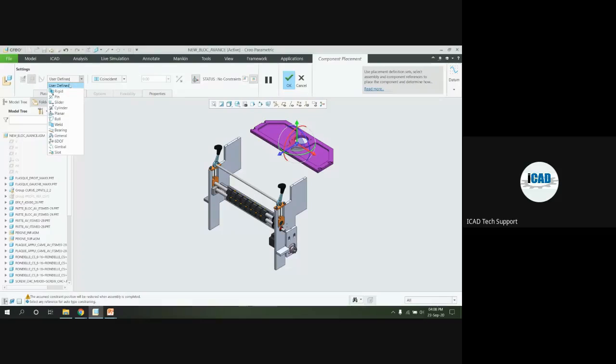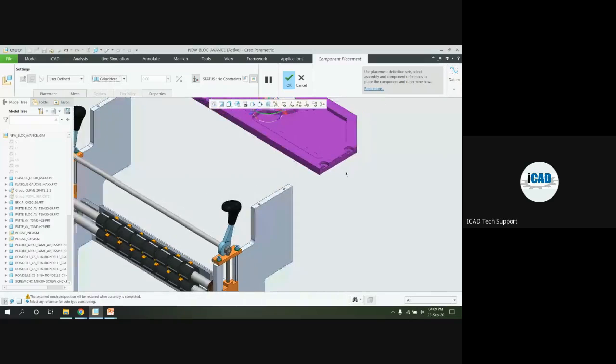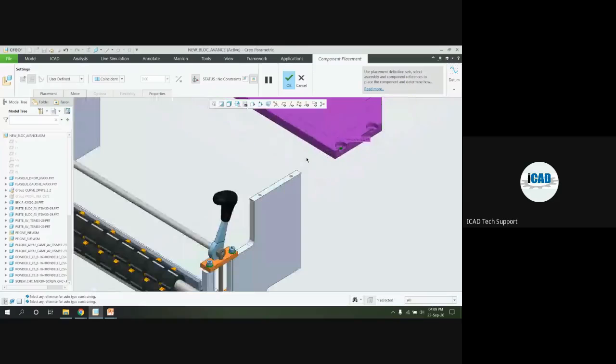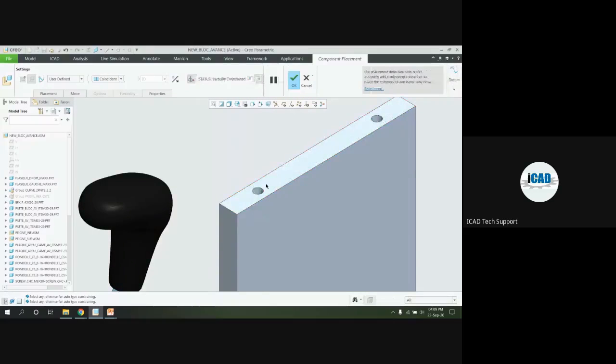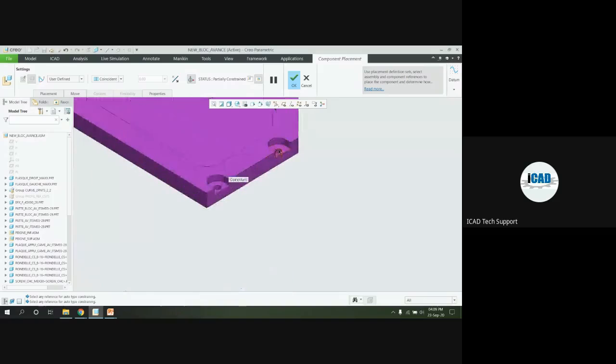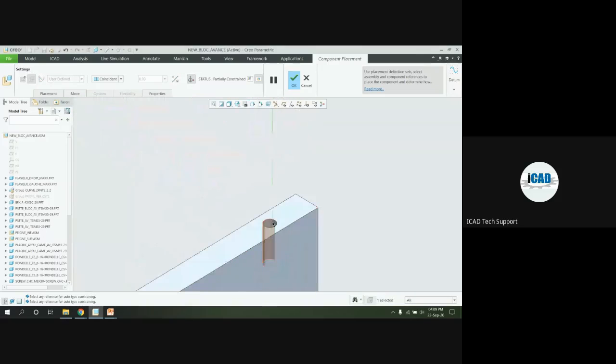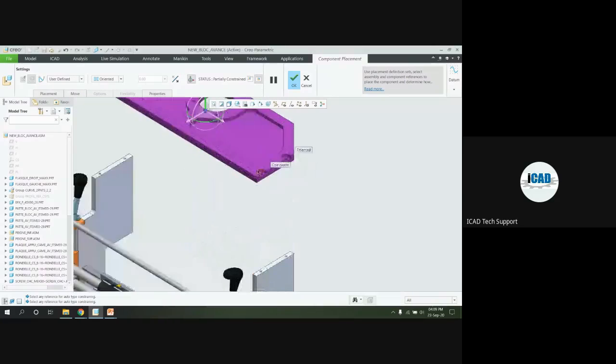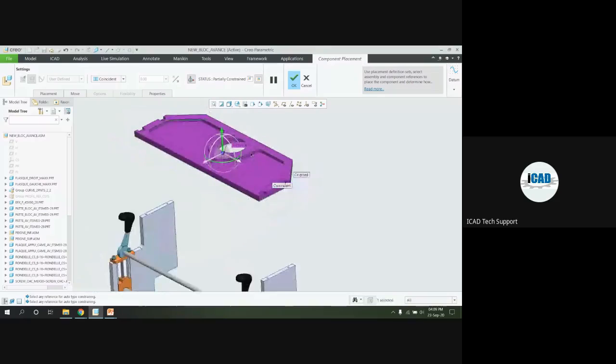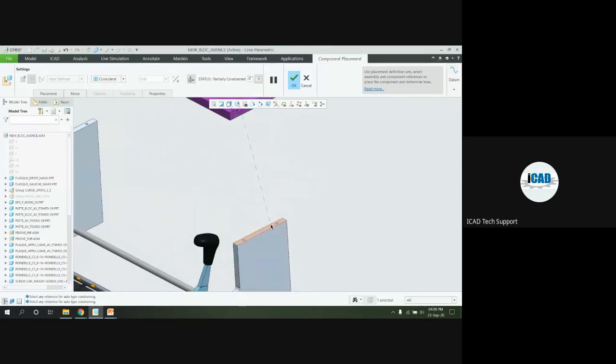If you want to run a mechanism, you can create pin, slider, cylindrical, planar, ball, and weld connections for the assembly. If you want direct coincident, the distance, angle, offset, parallel, and coincident options are available. Here I want the direct coincident option. So I am selecting these two holes for coincidence. Next, again this hole and this one. And for the bottom surface of this plate, I want to rest this surface on this specific surface.